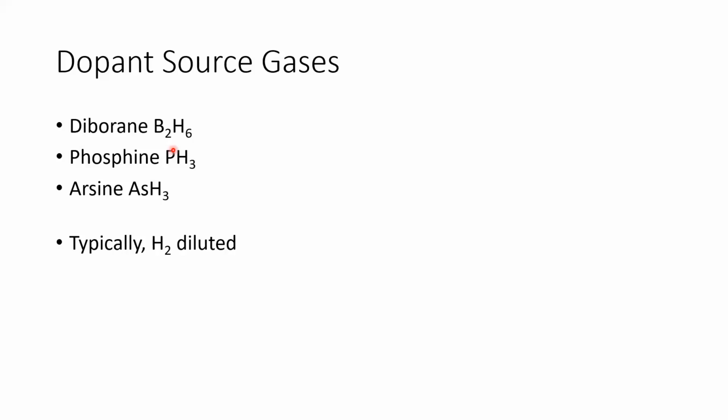I just want to quickly introduce the epitaxial process, especially VPE, vapor phase epitaxy. There is also liquid phase epitaxy, which is mainly for 3-5 compound semiconductors, and solid phase epitaxy. There are many more, like MBE and MOCVD, for 3-5 materials.